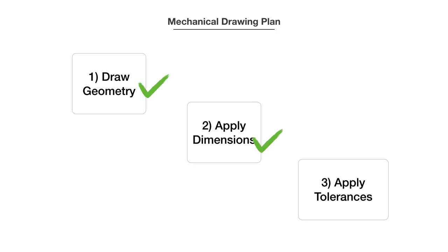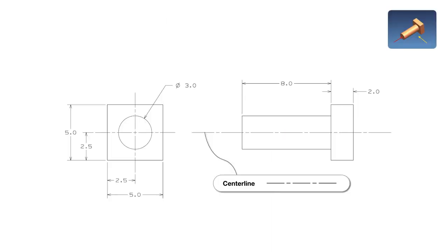Alright, we're back. Last step we have on our pin is to apply tolerances. I mentioned earlier that this part is good for my team, but it's not ready for going out the door yet. If I order this part, there's no way anyone will ever make a pin that's exactly 10 millimeters long, or 5 millimeters, or 15.32. Anything specific isn't going to happen.